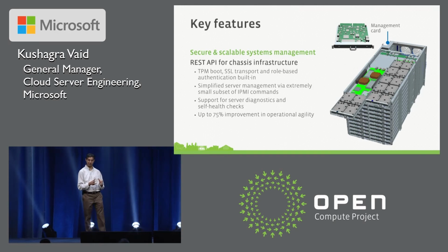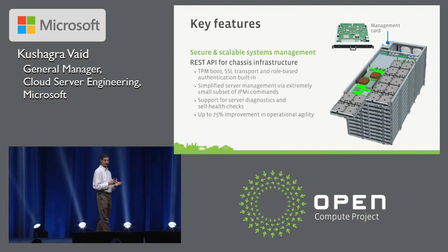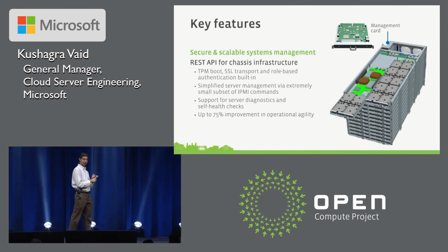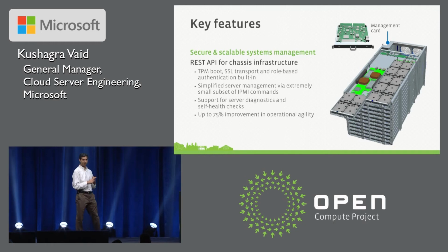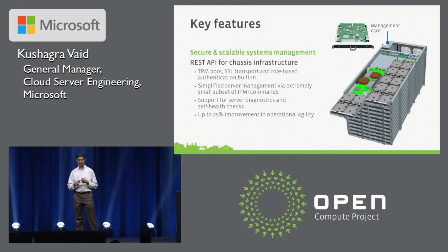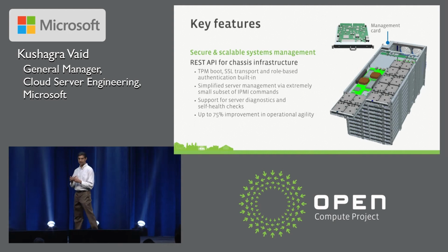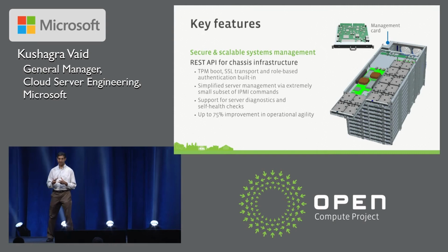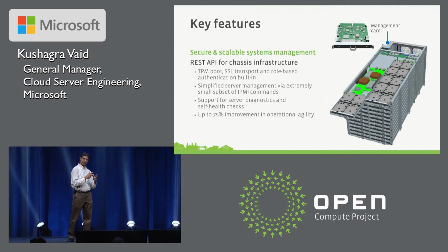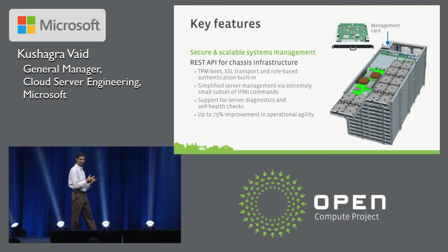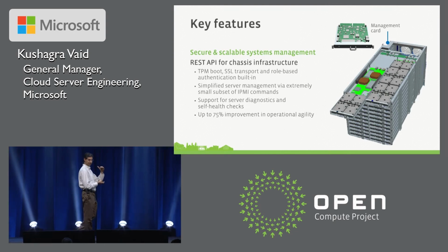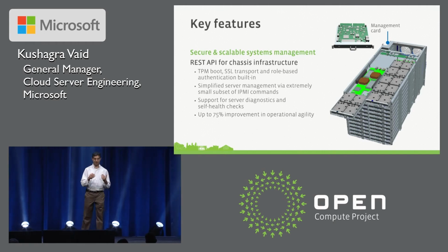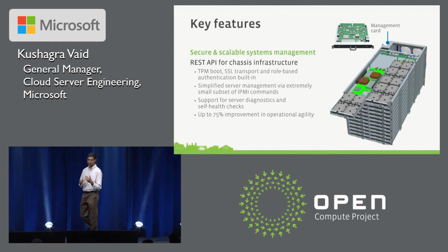So let me talk a little bit about the security aspect here. There are three things that contribute to the security of the infrastructure. The first one is the management card has a Trusted Platform Module, what's called a TPM, on it. So when you boot up the embedded OS on the management card, the boot is authenticated, and it gives you the assurance that there has been no violation of the golden code path that is running on the management card.